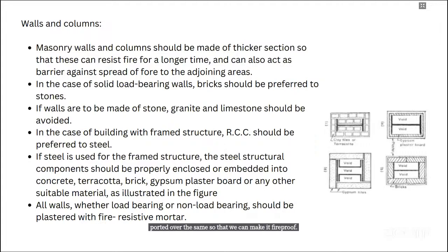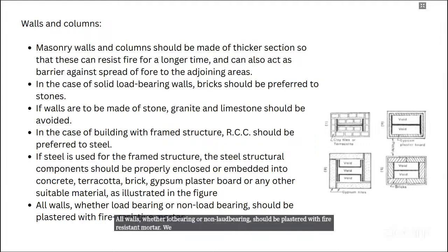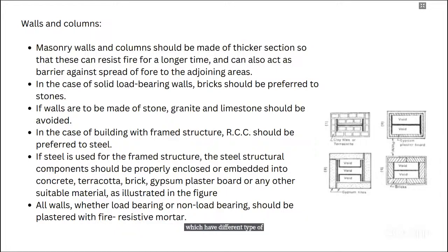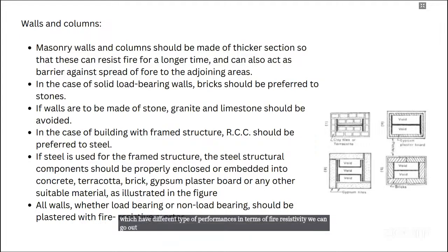All walls, whether load bearing or non-load bearing, should be plastered with fire resistant mortar. We have different categories of fire resistant mortar available in the market, which have different performances in terms of fire resistivity. We can always go out and understand the performance, and incorporate these materials in our designs. Next.